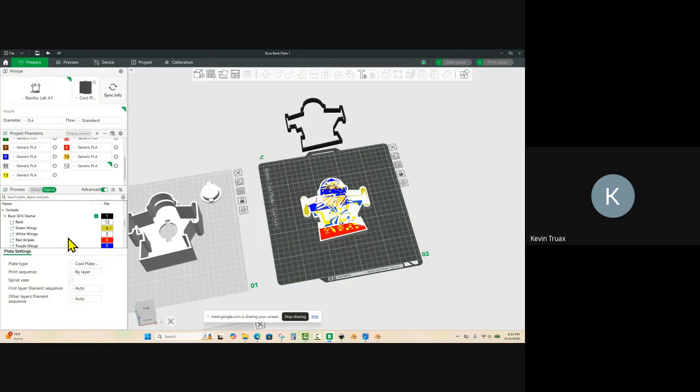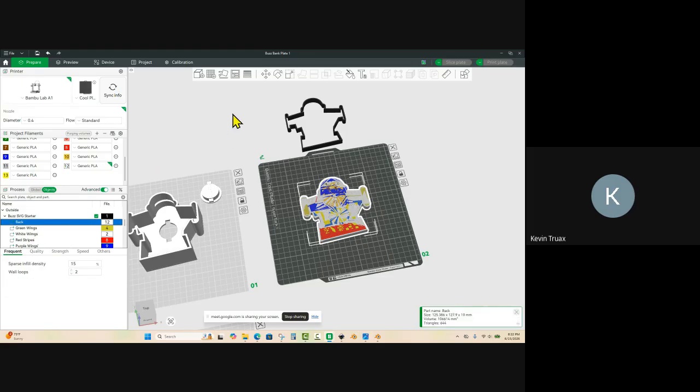And I have a good idea of how I might want to build this. So what we're going to do is change the thicknesses of things. So we're going to start here with our back, go to our scale tool, and we want that to be 4 millimeters thick. When I say the back, that's actually the front plate. That's going to be our front plate, 4 millimeters thick.